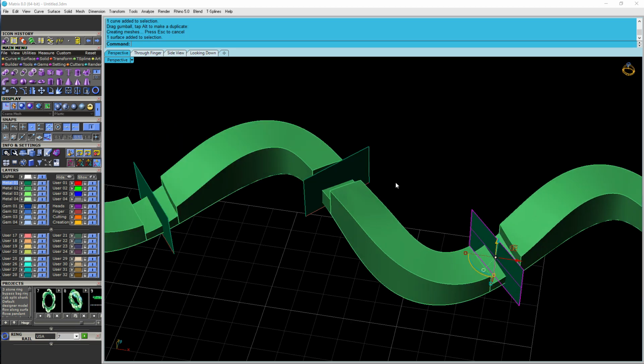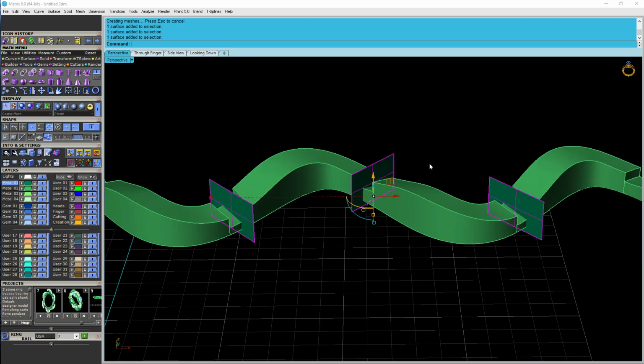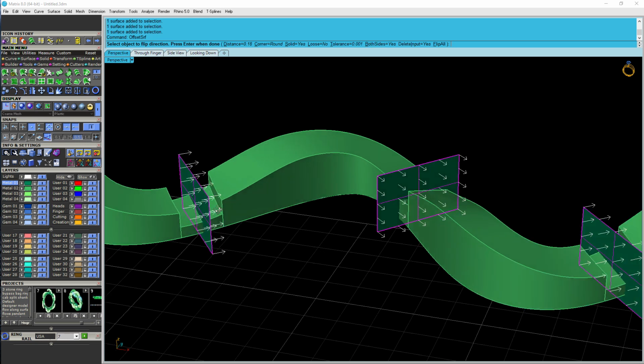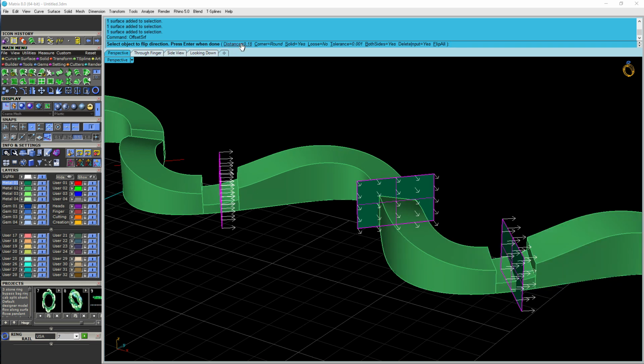And we want to use this as a Boolean. So to make a single surface a poly surface, you need to type in offset surface. We have both sides equal to yes, which we do want because we want to create a small bit of separation between that. We're going to say solid equals yes, both sides, and distance. Let's go with maybe 0.06 divided by 2, so 0.03, and then right click.